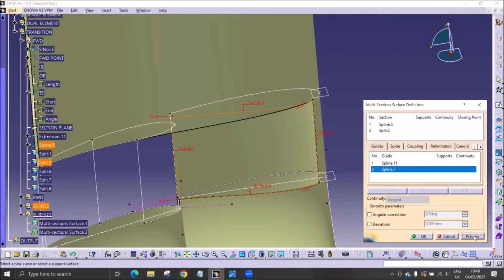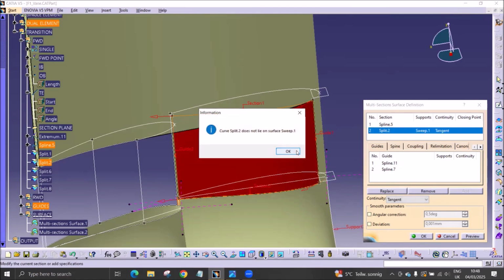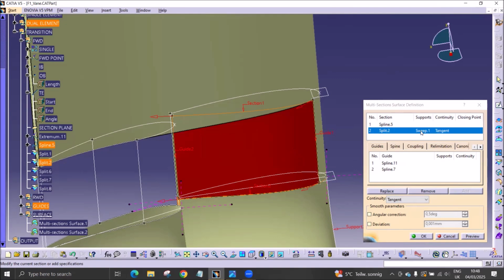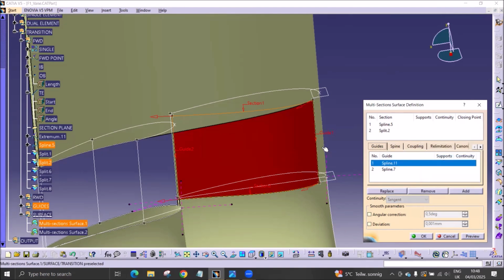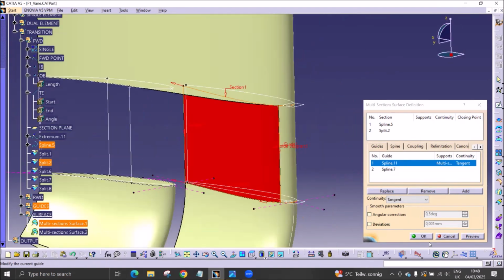Okay. The preview button, very important before you apply the tangencies. Try that. So it could build the surface before, but now that I wanted to apply the tangency, CATIA has the problem that it thinks that this line doesn't lie on the surface, which is nonsense, but this is CATIA. So we need to convince CATIA that it's really lying on top of that surface.